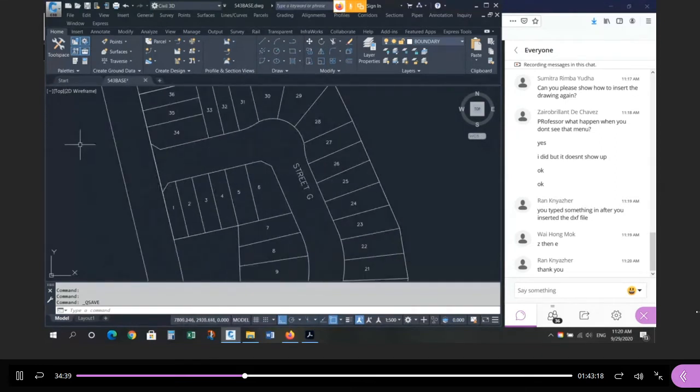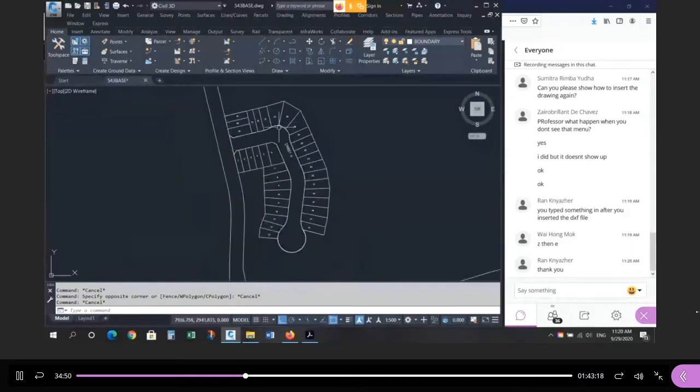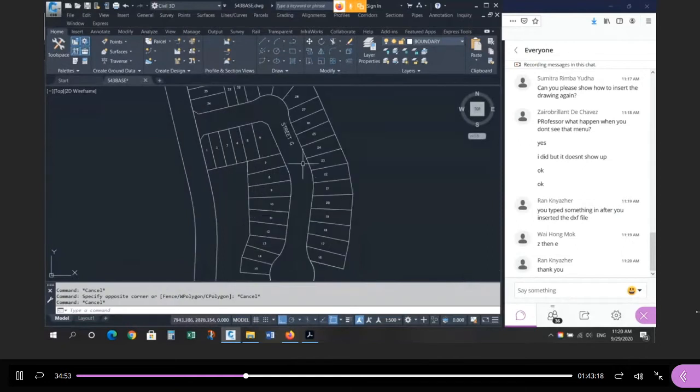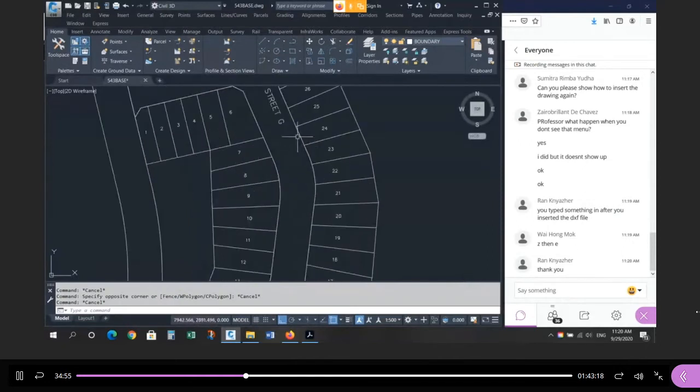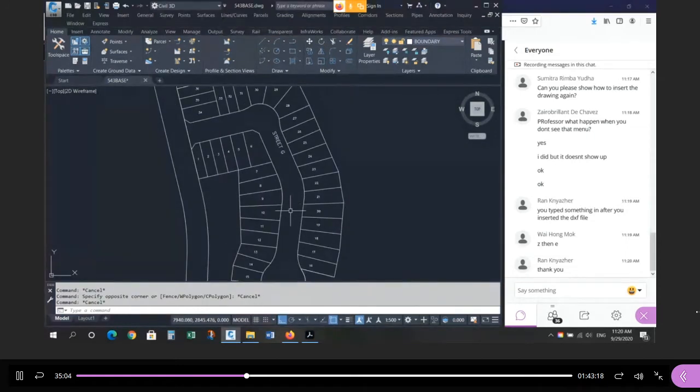tell me, don't go near the intersection, don't go near this bulb, this kind of crescent or bulge here in the corner. Everybody's got one of those. And don't go anywhere near the bulb, like the dead end part. Somewhere in the middle, measure the distance across. How wide is the right of way? So measure the distance from a near point perpendicular across the street. How wide is the road? This is the right of way.